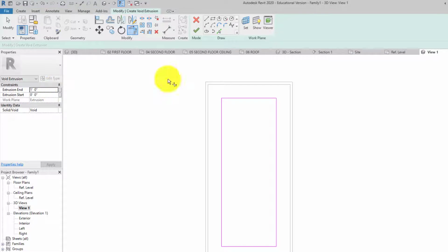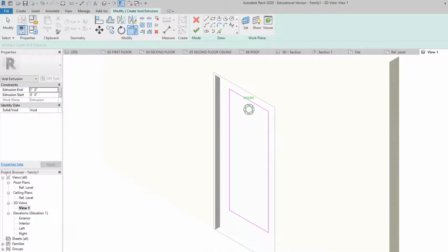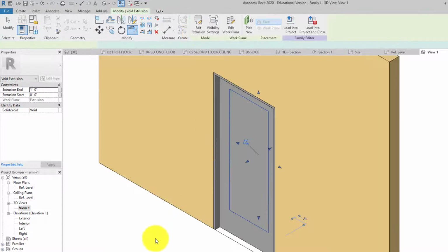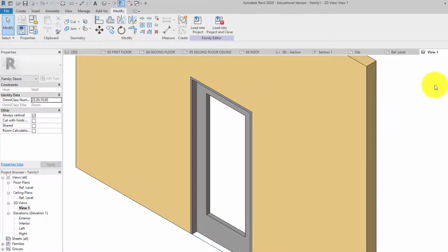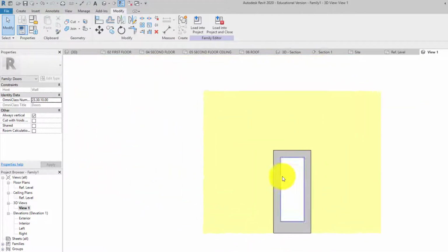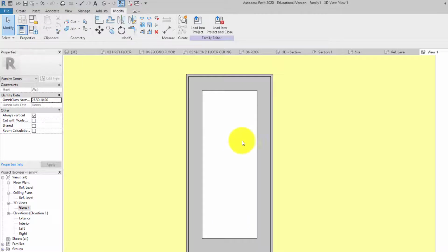And the depth is a foot, so depending on which way this goes, if it goes out towards me, it's not going to do anything, but if it goes the other way, it's going to be perfect. So let's click check and see what happens. And it worked. It went the other way, it went a foot deep, and you can actually see it right there. Now we've cut out that portion for our glass. But before that, let's go ahead and make some muntins, those little tiny divider things that show up.